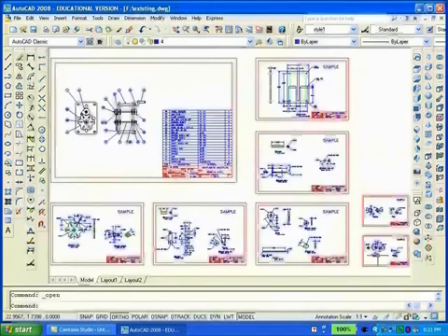Regardless of the scale of a printed drawing, when drawings are printed in either model or paper space, they have to be consistent. All companies want dimension, text, and text height to be standard sizes. Out of necessity, there have to be changes to the variables of dim scale and LT scale, I call it light scale.